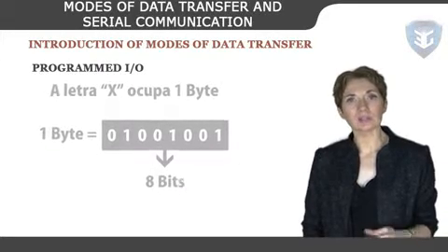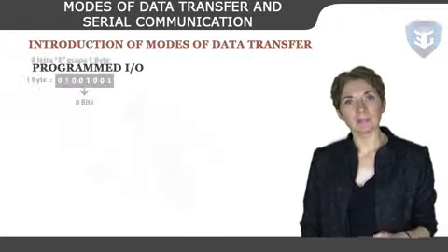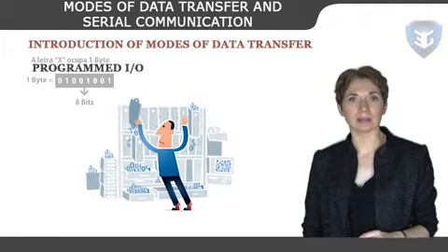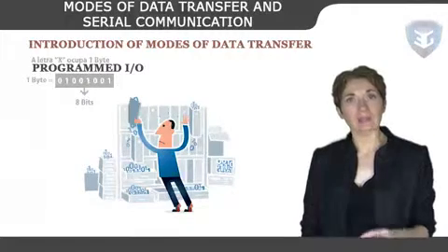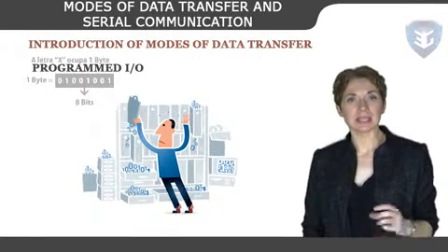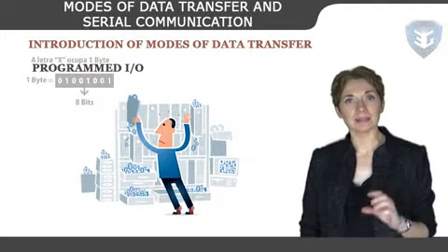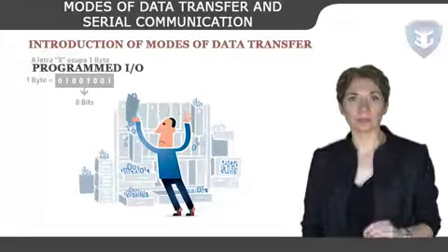When a byte of data is available, the device places it in the I/O bus and enables its data valid line. The interface accepts the byte into its data register and enables the data accepted line. The interface sets a bit in the status register that one will refer to as an F or flag bit.